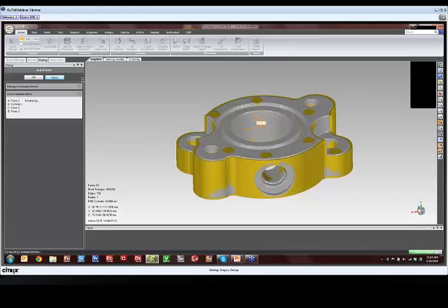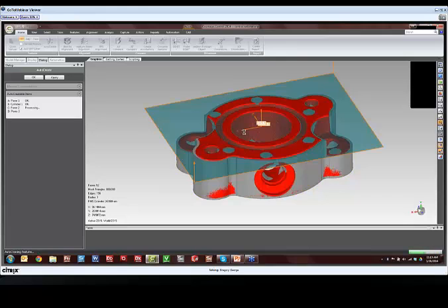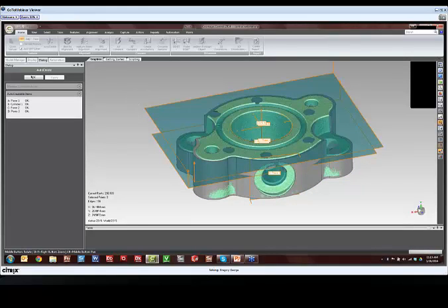And the reason why I'd want to do that is on the CAD model I have those perfect datums in space, and I may have to select that geometry and fit a plane to the top of the flange here in order to fit an imperfect plane, so I can measure the deviation maybe of the direction normal of that plane.